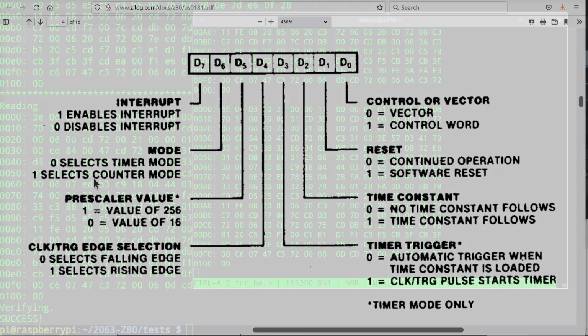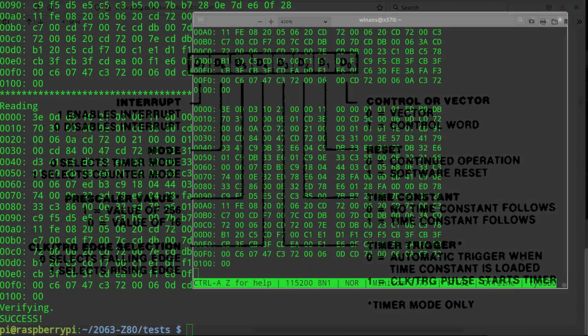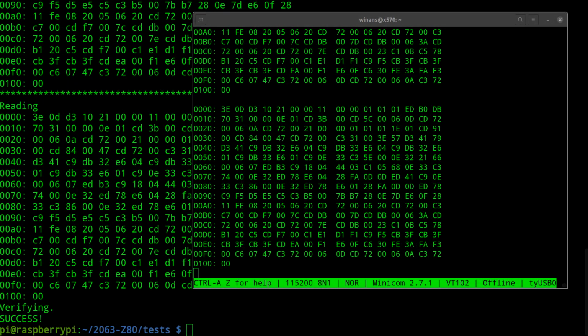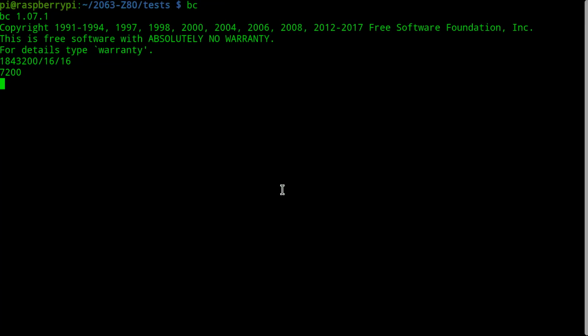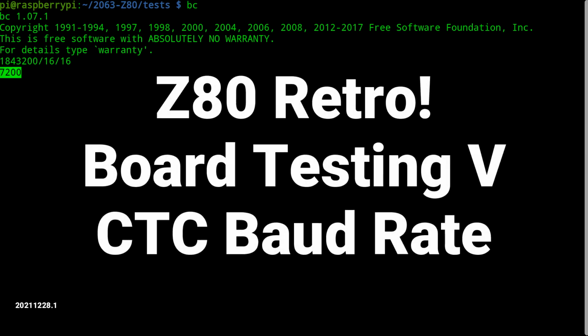Keep aware of, though, that in timer mode you have to use one of the prescalers. So it's going to divide your speed down by 16. So your maximum bit rate, if you use that as your oscillator, will be limited to, I don't know, 9600 baud or even less for the top speed with that size crystal. But it's still an achievable thing to do if you want.